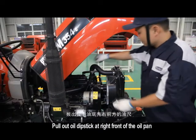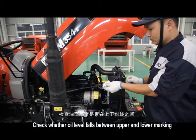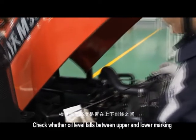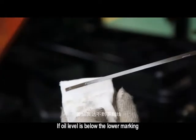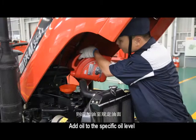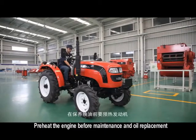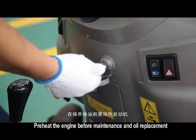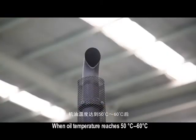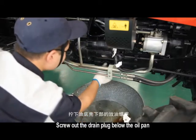Pull out oil dipstick at right front of the oil pan. Check whether oil level falls between upper and lower marking. If oil level is below the lower marking, add oil to the specific oil level. Preheat the engine before maintenance and oil replacement. When oil temperature reaches 50 C-60 C, screw out the drain plug below the oil pan.